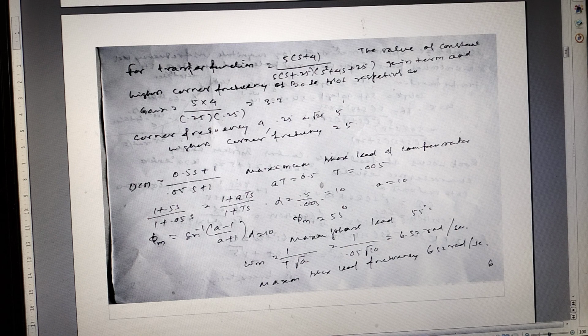This is for the state variable system. Roots are in the right half of the s plane. The system is unstable, and for controllability, the matrix is checked. Its determinant is equal to 0, so not controllable.